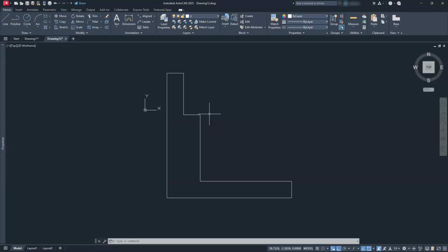I'm going to go ahead and start putting in some of my surfaces that I do know where they are. Let's go ahead and use the offset command for that. So I'll go to offset and I'm going to start off by creating this one here at the bottom. So I'm going to offset, I'm going to put in that distance of 50 since we determined that that's where the center of this is located at. And I'm just going to go here and place it here.